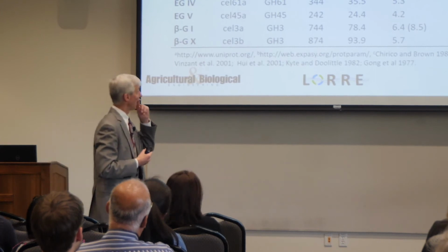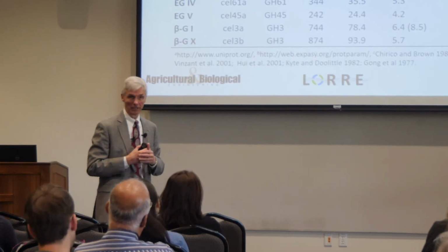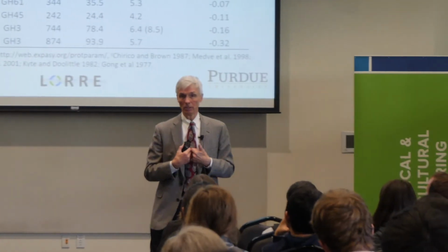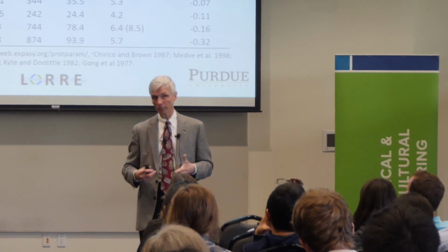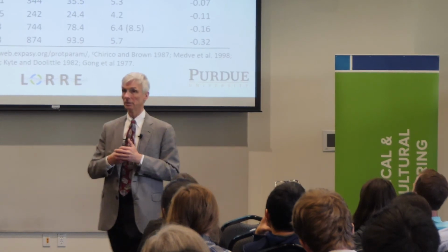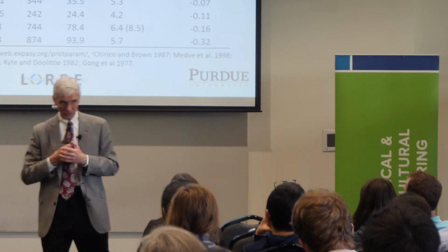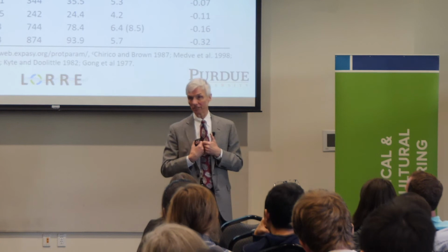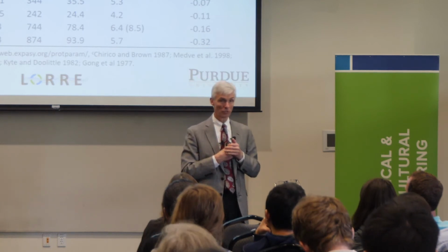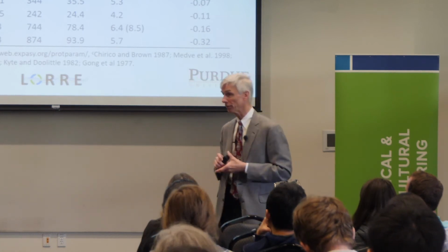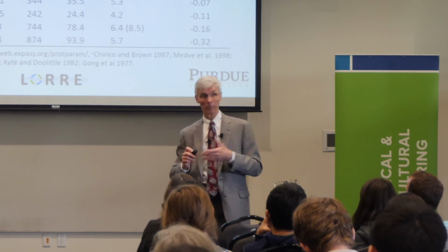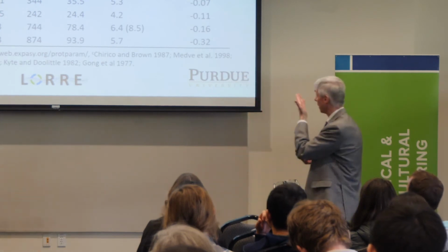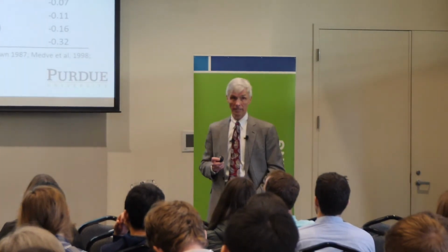All right? And then you have hydrophobicity. So that means they have different propensities to absorb with the substrate, with anything else that's in there. And realize when you're working with wood or corn stover, you're introducing dirt. Every once in a while, a metal, bolts, wood chips, I mean, you name it. So this is not your reagent-grade cellulose Avicel, which is ordinarily used as excipients in aspirin, but also used in labs for qualifying whether an enzyme activity is good or not. Okay, so all these properties had to be considered as we scaled up.